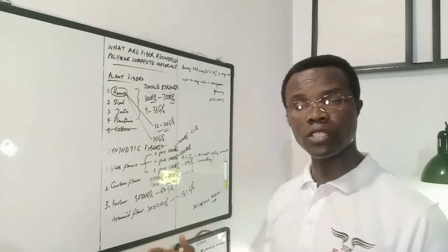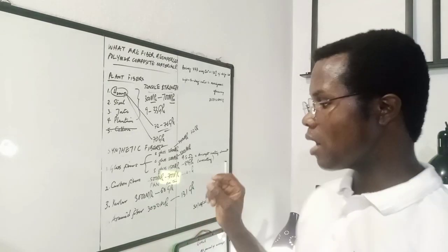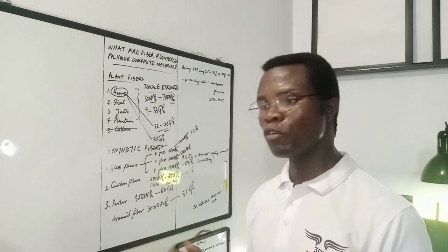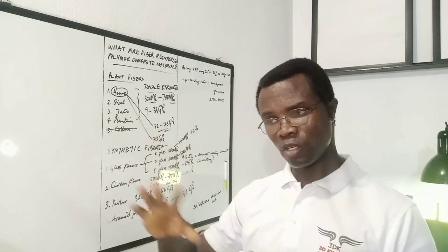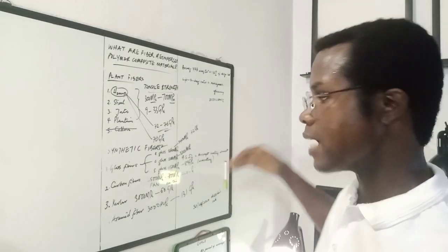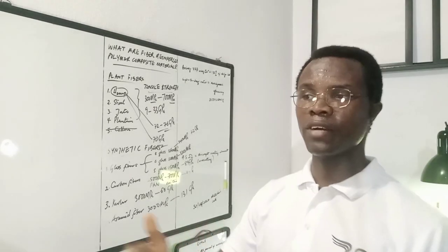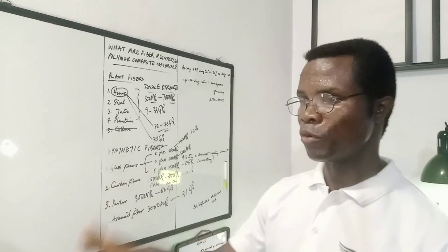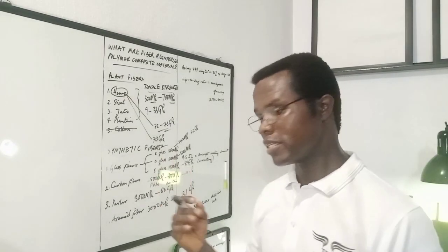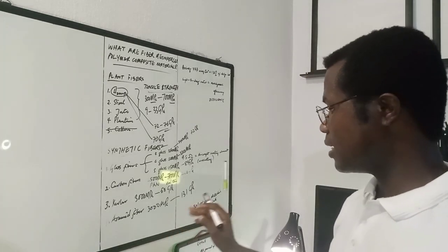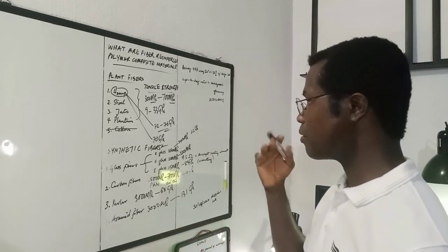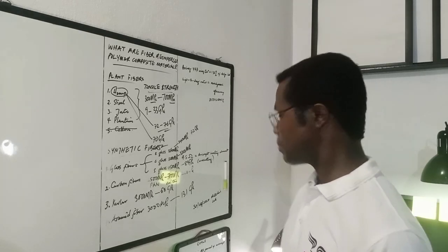For the carbon fibers, the precursors, either polyacrylonitrile or coal tar, are soft. They are polymers that can be drawn in that way before they are then treated and carbonized properly through a very special high temperature process. They start out as polyacrylonitrile fibers, and then having been subjected to many processing steps in that furnace-like system, it's a production line basically, it eventually arrives at the other end as carbon fibers. So these are the key details to have in mind about these fibers.